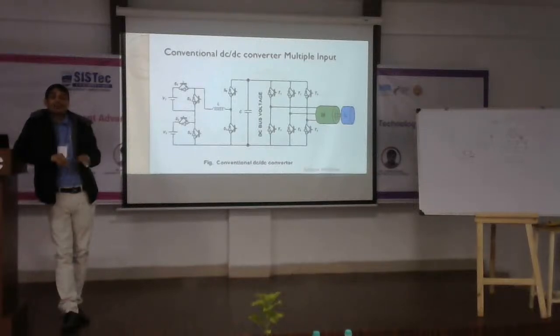So again, we need to filter out these harmonics from the source. Getting my point? You are taking power from the same source and deteriorating it. What was the benefit when we used tungsten-based bulbs? There was no power factor loss, the power factor was unity, and there were no harmonics.